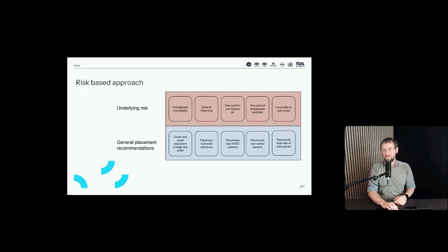You raised a really good question, that your requirement is basically that it needs to be below 30. And in that case, it really doesn't make a whole lot of sense, when we take the risk-based approach, to have a sensor in the cold spot. The same thing goes for ultra low temperature freezers, for example, ULT freezers, normally operating at, let's say, minus 70 degrees Celsius, and fridges operating where it just needs to be below minus 20 degrees Celsius. It only makes sense to find the hotspot, because whether it's minus 25 or minus 30 or whatever, it doesn't matter for the efficacy of the product. Really good question.